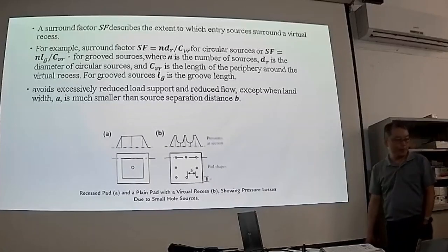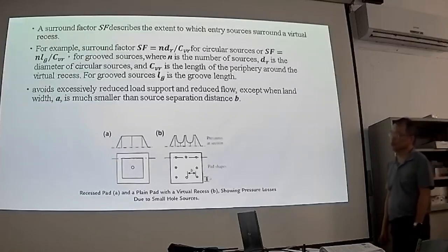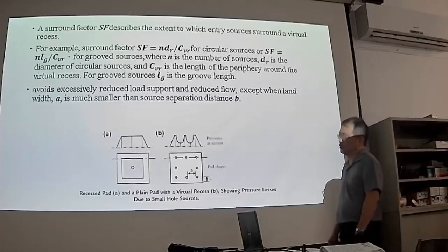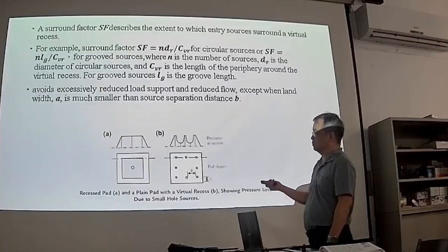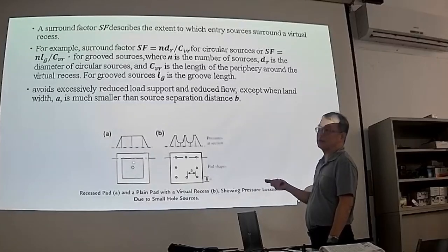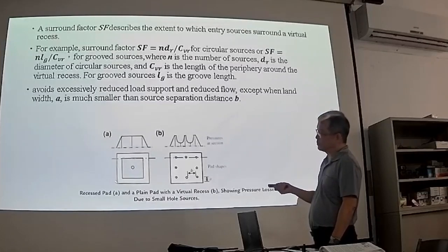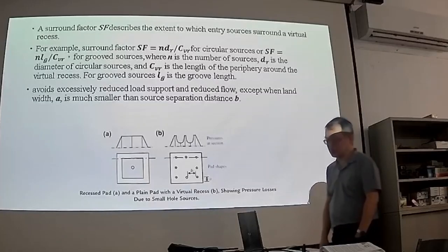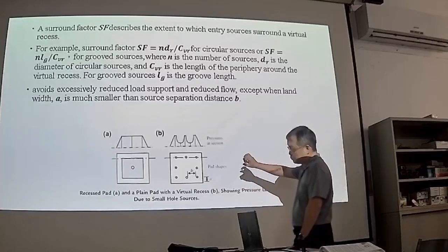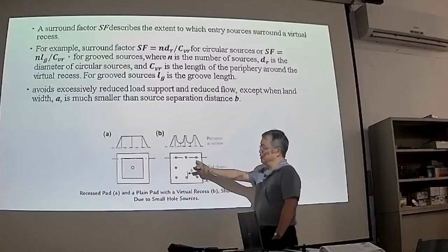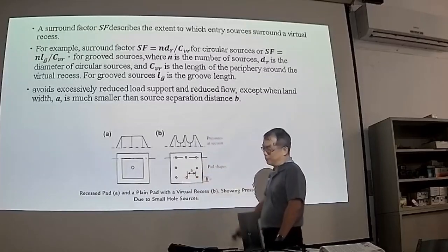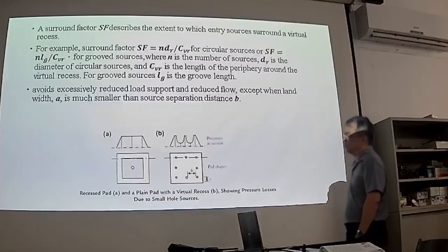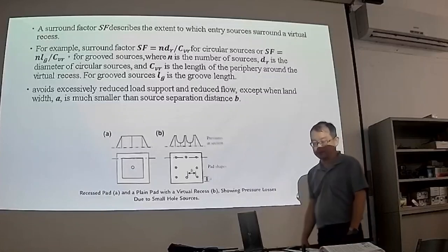For air bearing, due to the symmetrical instability, we tend to design the air bearing without recess. But we try to increase the stiffness or increase the recess pressure during the pad area or inside the pad area. Another alternative way is using the virtual recess.